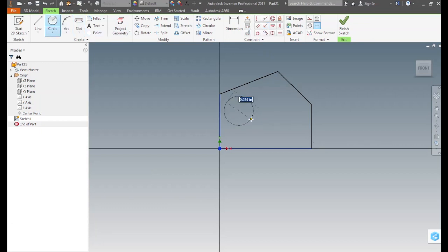Let's demonstrate another constraint, in this case tangent constraint. We will draw a circle, and apply the constraint between the circle and each of the adjacent sides. Let's use the Trim tool, and now we have a fillet. We can apply a horizontal constraint to 2 points too, they will be now at the same distance from the x-axis.